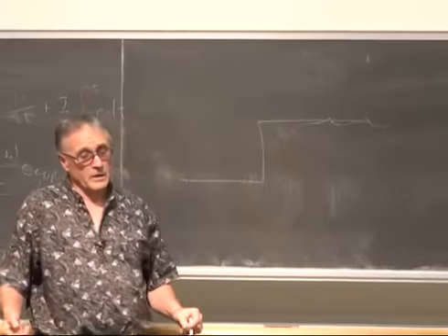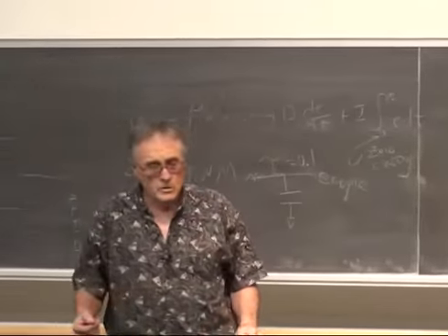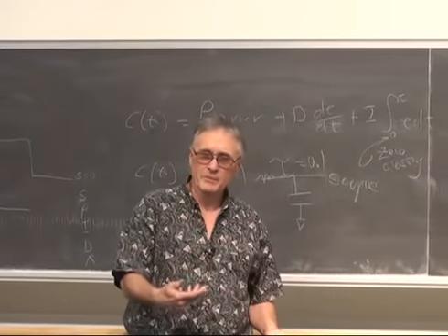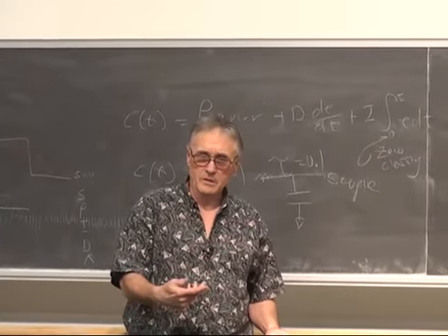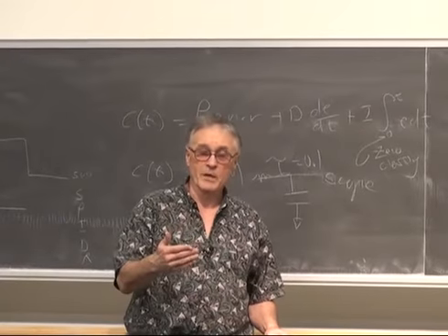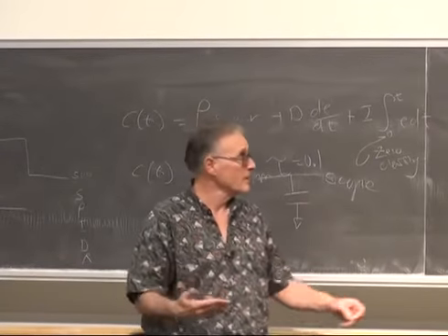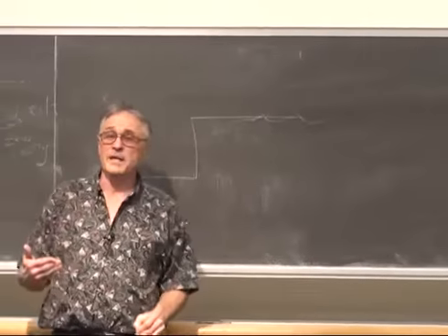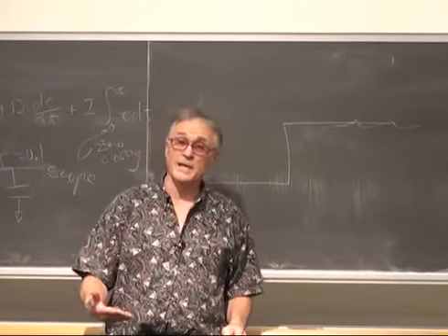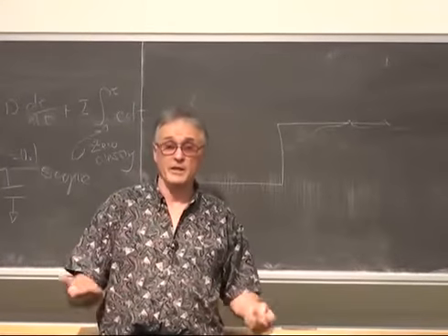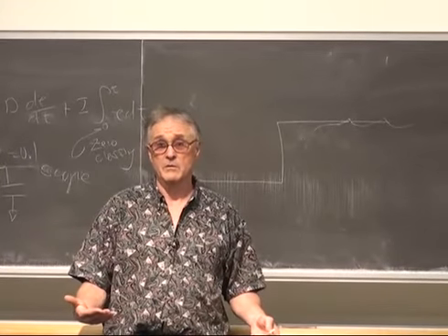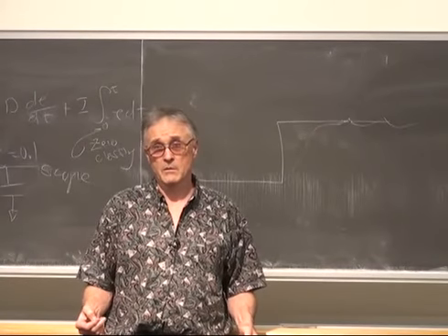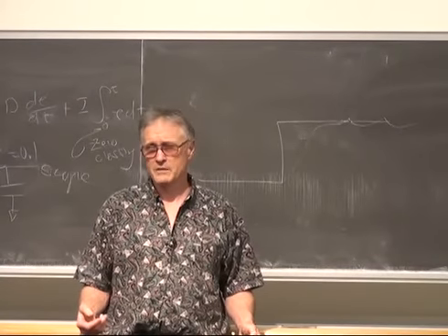And you don't want to integrate it for too long. The average should be 0, but it won't be because of noise. So one parameter, say, if I'm crossing the criterion speed, I should reset because that gets rid of any accumulated noise, and I know I'm at the right speed, so the integral term should be 0, or all of the error should be 0. That makes sense?